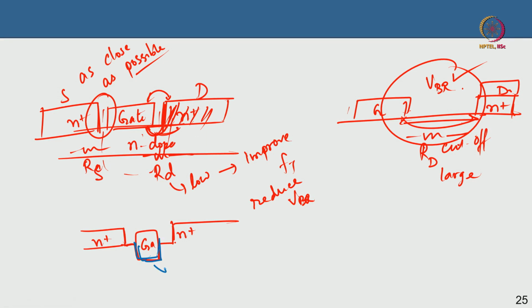So this recess helps improve breakdown voltage, alright, and have a better channel control, so better GM as I already told you. This spacing will also dictate your breakdown, but again you do not want it to be too close or too far, it depends on the design that you have, okay. But double recess is all about improving the trade off, breakdown and cutoff frequency, breakdown and GM, okay, that is all the trade off is, the double recess.